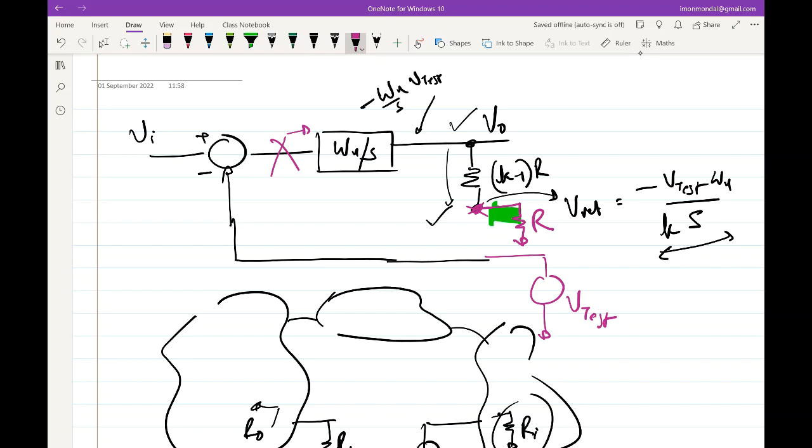So the operation of the loop should be such that the loading at each node of the loop remains untampered. Okay, so that's the whole purpose of it. Sometimes in some circuits, it's easier to find a location where even if you break it without taking care of the loading, things are fine because maybe it's a high impedance node. If it's a high impedance node, you probably don't bother because nothing needs to be translated. But in some cases, you will find that it's not high impedance, so you'll have to take into account these things.